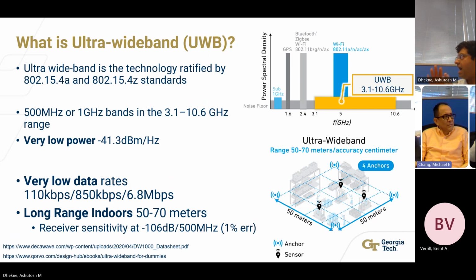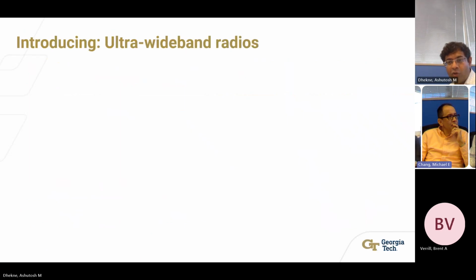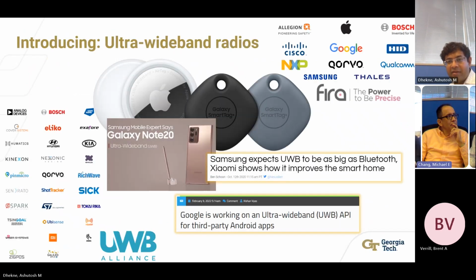So we need algorithmic solutions to cancel out these clock drift and clock offset errors. The original algorithmic solution to do that had a problem. It required both devices to be equally capable. Only then did it work well. But then in 2016, the company Decawave, which features here as Qorvo, the company who bought Decawave, came up with, actually not even an algorithm, just a formulation that allowed mitigating the clock drift error. Once they did that, it opened up this localization space.